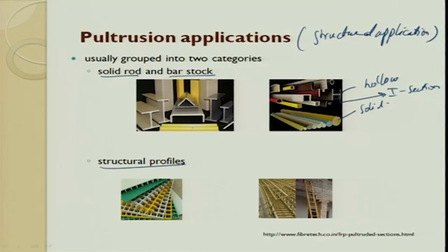You can extrude; whatever can be done by extrusion process can also be done, but the only difference is that here you will have matrix and fiber, whereas there it will be only matrix. Here it can go for high strength, and on top of the polymer you can also give a metal touch. Then it looks as though it is a metal aluminum channel, but it is made out of composites by the pultrusion process. So, this can be made, and these stocks can be made.